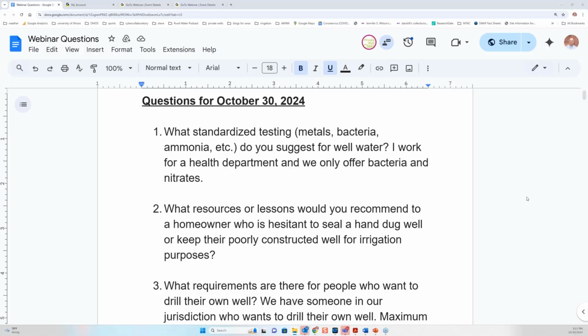You know, if you're actually taking care of the well and you've made it so it's safe, that no one's going to get hurt, I'm not saying it's not okay to keep a dug well around, as long as, one, it's not anywhere near your existing well and your new well, if you have a new well, and where you're getting your water from in your new well is much deeper, and there's protective geology in between, so that there's no risk that something gets in that well and dies and causes all kinds of issues, that it's going to leach down into the aquifer.